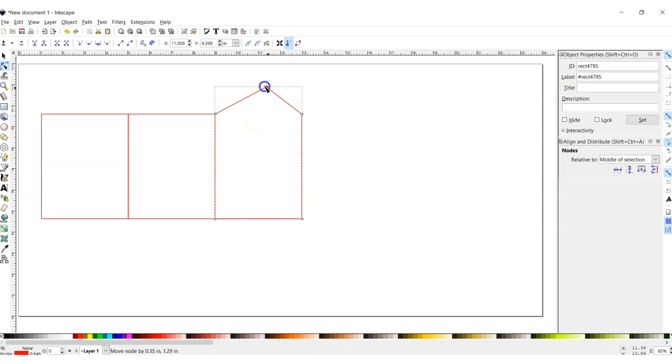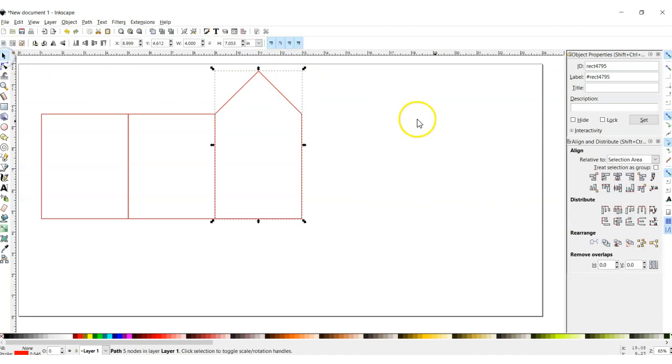Now if I click on it and hold down, I can drag it up and down. Okay. Now I want it centered. So if I'm near the center and I hold down Control with my left finger, I'm able to drag it and keep it symmetrical. So I'm going to drag it up like that and click select, and I'm happy with that. So that's about 7 inches tall.